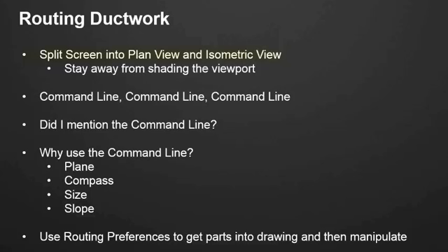I prefer to split my screen into a plan view and an isometric view into two different viewports. That way I can see what is happening in plan view where I do most of my drawing, but right on the other side of plan view I can also see it in 3D view immediately, and this has some advantages of being able to change your elevation by grabbing and stretching the grips on your duct, which we spoke about in previous webinars a couple meetings ago.